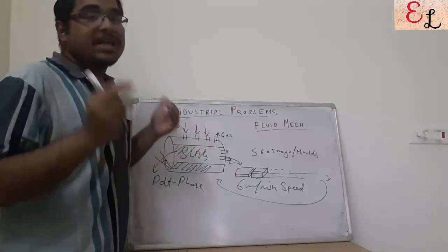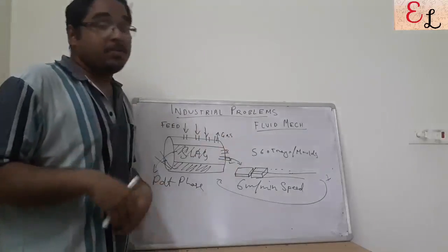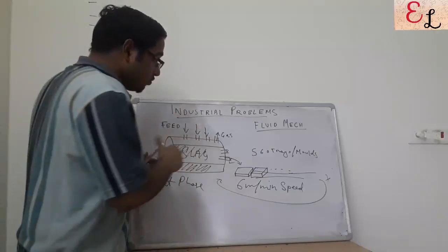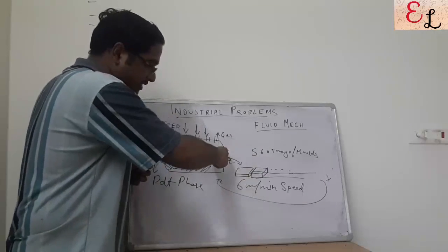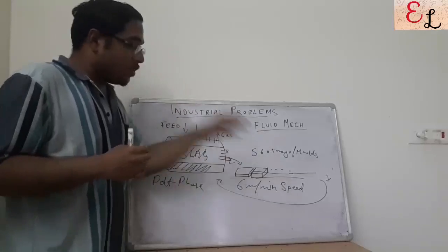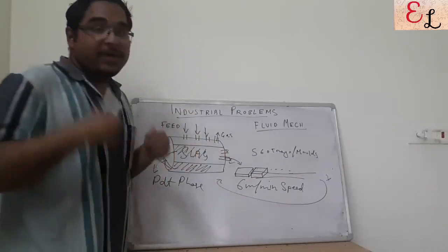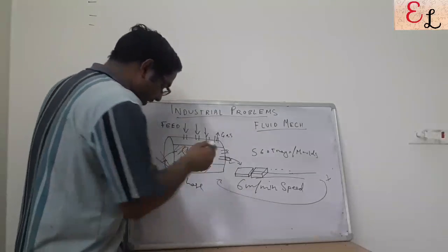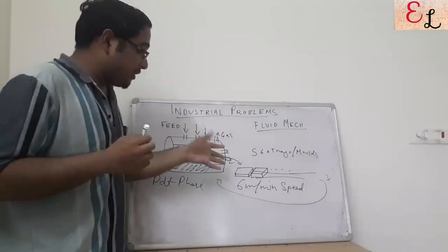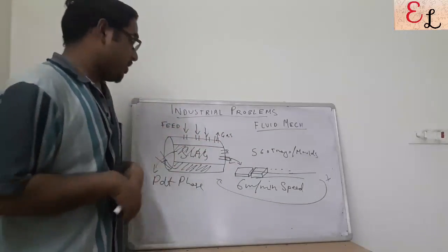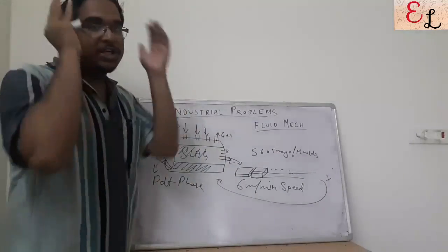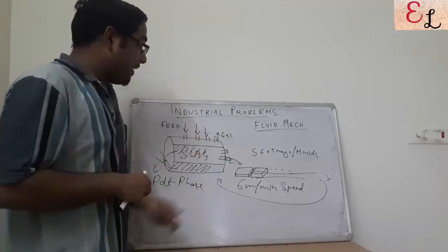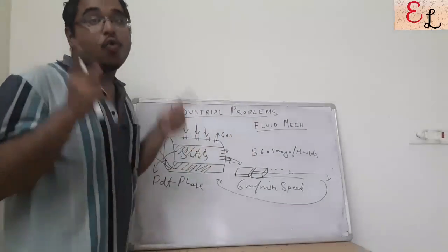What if increasing the tapping frequency is not possible due to unavailability of manpower, or because if we open this slag tapping hole more frequently, there is continuous exposure of this lance to hot metal, and this lance, this particular exit, might be damaged? So what if, keeping the duration between the two tappings as 2 hours, how can we optimize the speed such that no overflow occurs?